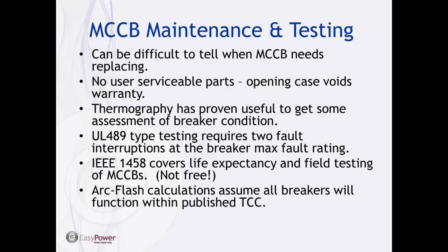We'll talk about some of the standards we mentioned that cover assessment of breakers that are in service for inspection and replacement testing. One of the things that's proven useful is infrared thermography of the breakers to assess some breaker conditions that indicate the breaker should be replaced.